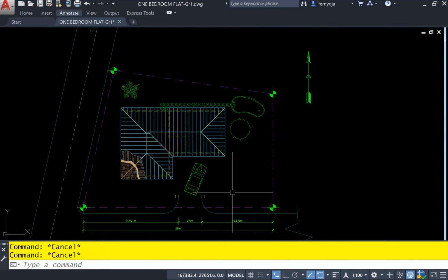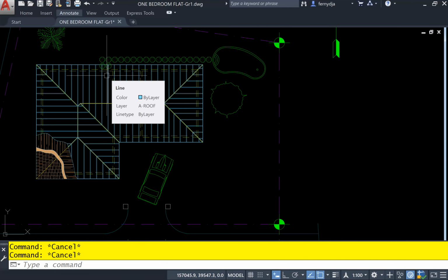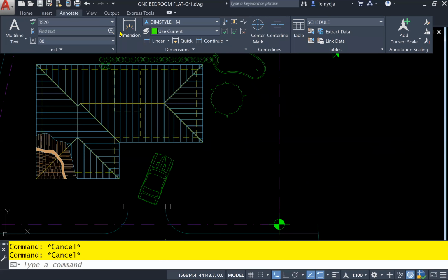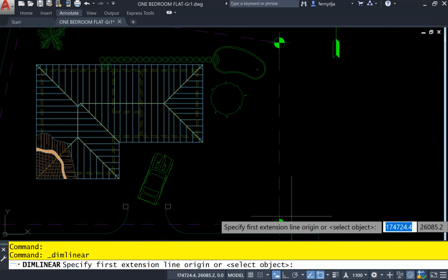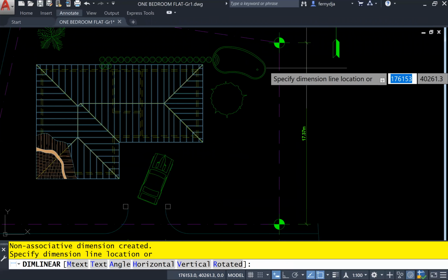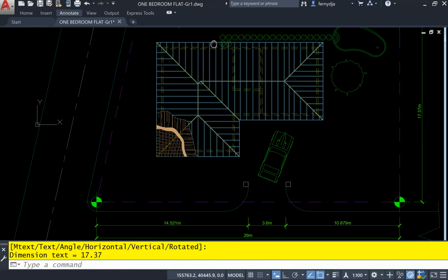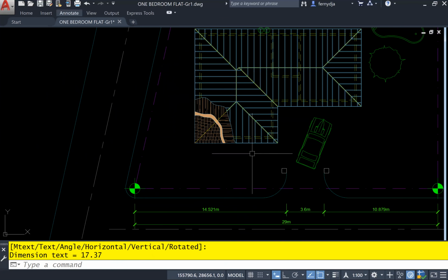All right. Now we're going to put another measurement in, going vertical. This is exactly vertical, so we can use Linear. It's only when the line or the boundary or something is at an angle that we use a different tool. Soon come to that. So let's go with Linear again. Then we're going to pick center of circle to center of circle, pull out and click to place. Likewise, here we have just 2 more linear positions to put in. So press enter to repeat the command.